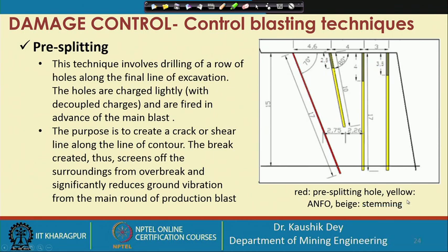Pre-splitting is another type of control blasting technique, where closely spaced holes are placed, just like line drilling, in the final boundary area, and these closely spaced holes are charged lightly and blasted ahead of the main blasting holes.